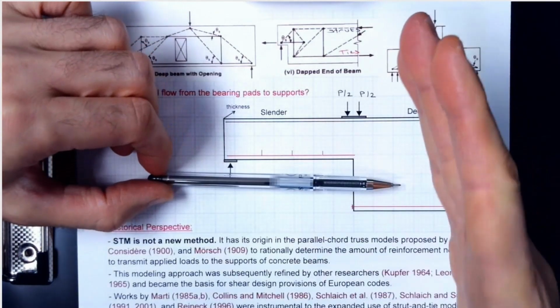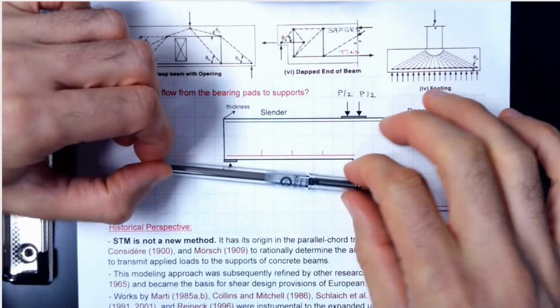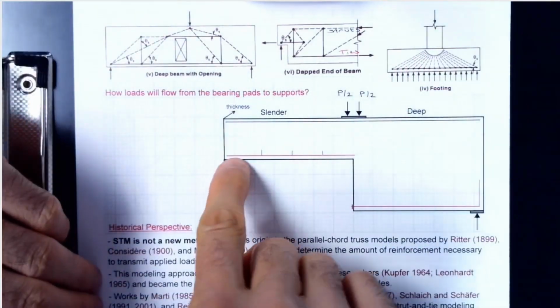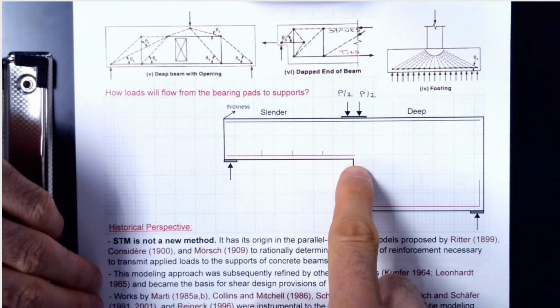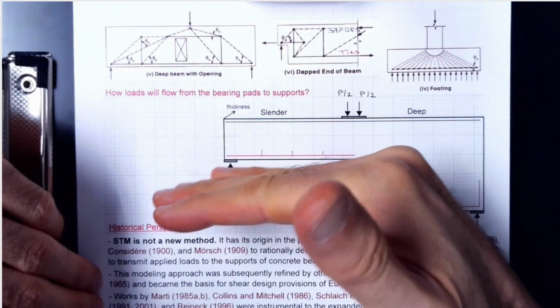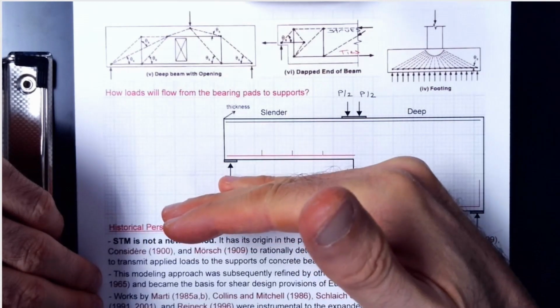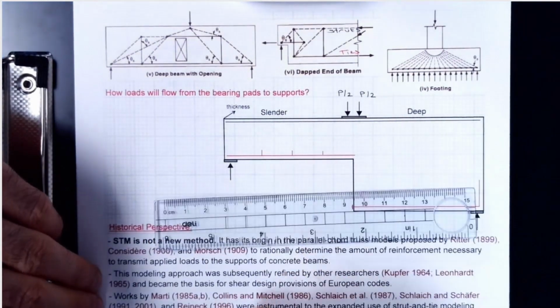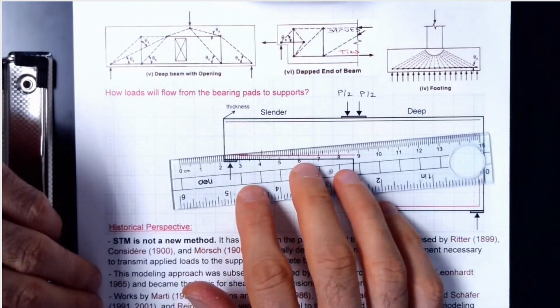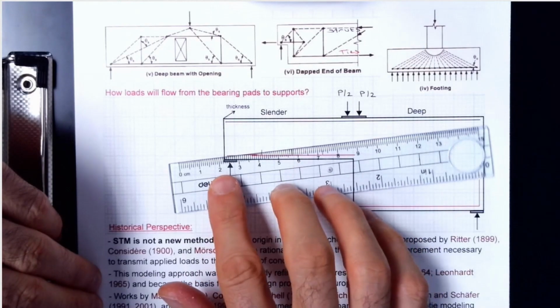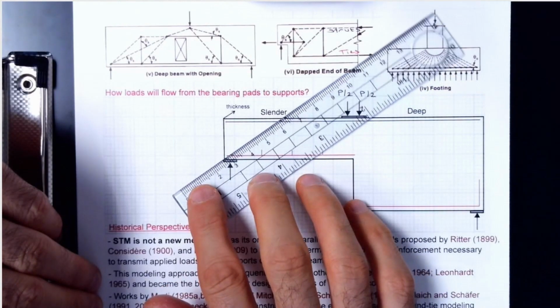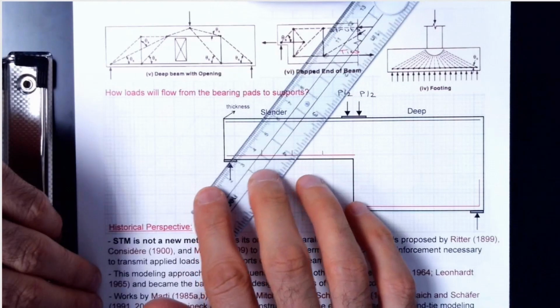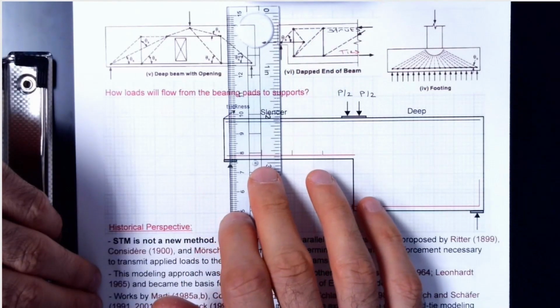You have principal stresses, you have tensile stress. The red indicates reinforcement, so it indicates there is tension which is horizontal. For this one, right, you cannot get compression horizontal, so you want compression to be maximum angle with tension, ideally 90 degree, right? The larger the better.